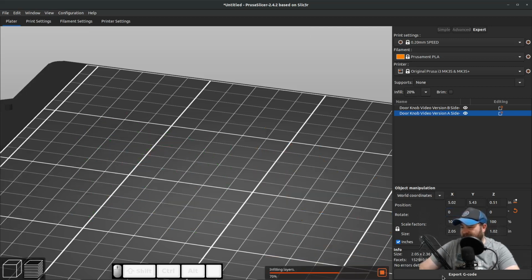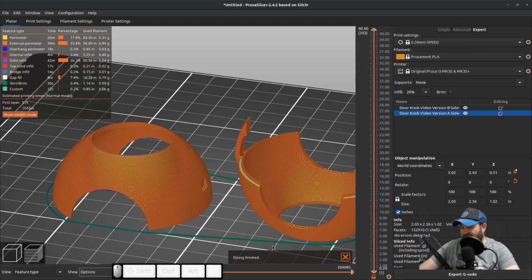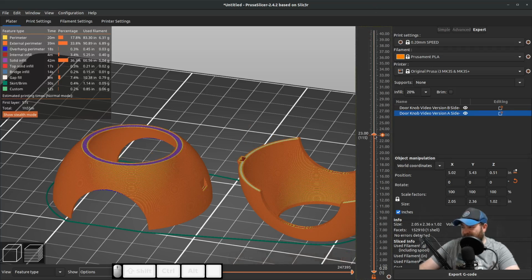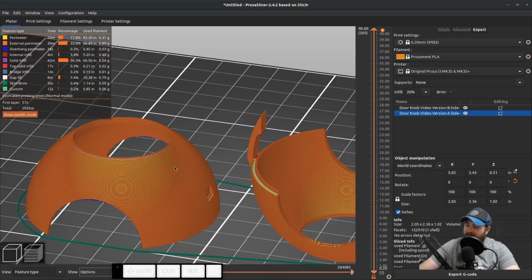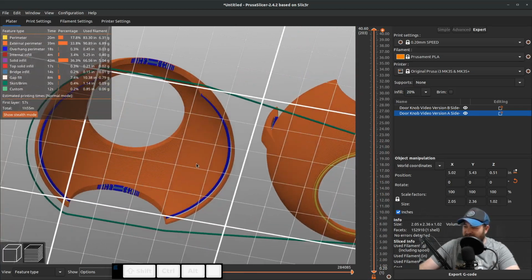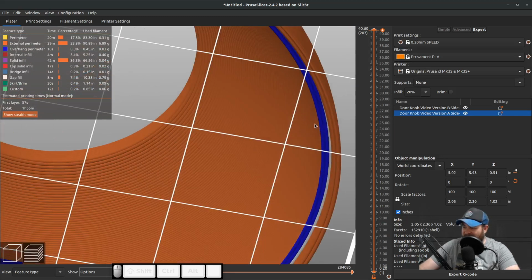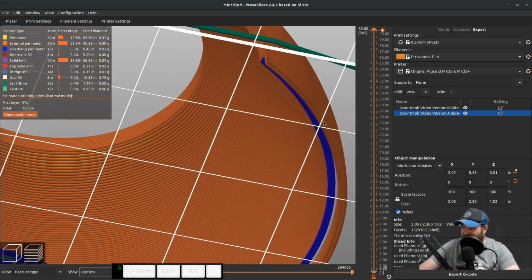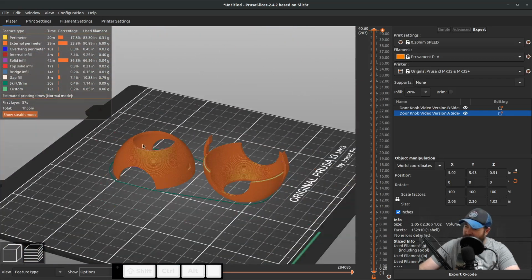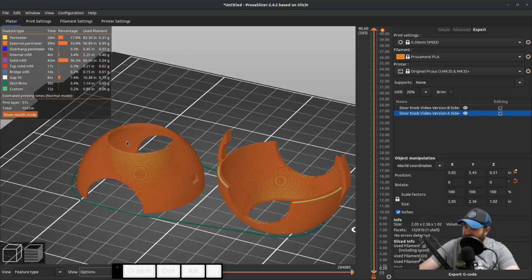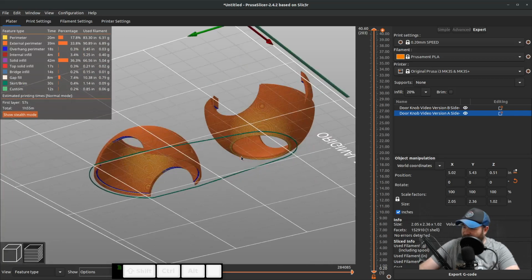And if I slice now, notice we have an extrusion on the first layer for both of them. All right, we can take this down. There's our first layer extrusion. So we're oriented correctly, but as you can tell, we have these blue overhangs. And it's too bad these are labeled as overhangs because I really wanted that chamfer to stop that overhang. But we're going to have a lot of infill inside of this anyways, and a little bit of infill in here.